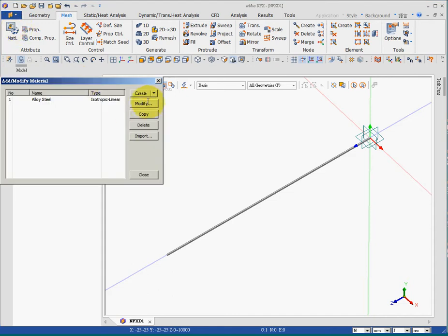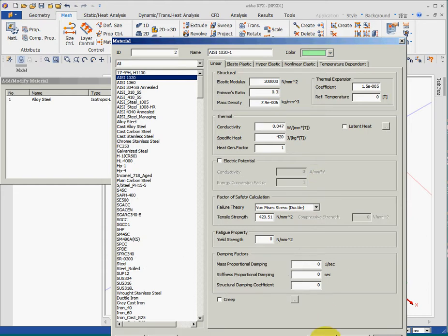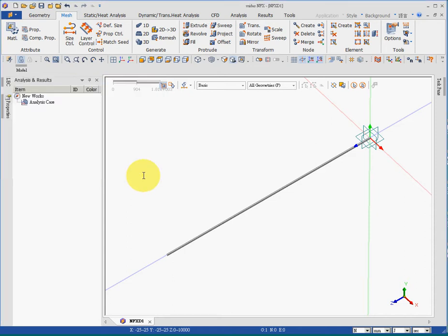So we load the material, isotropic material, 1020 mild steel, and I'll change the Young's modulus to be 3 times 10 to the 11 and Poisson's ratio of 0.3 to make my calculations easier. In this way, the theoretical natural frequency value will be 0.49 for the first mode, and the second mode was 3.14. So we can confirm the result. So this is the loading of material.